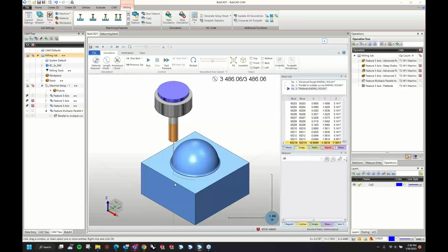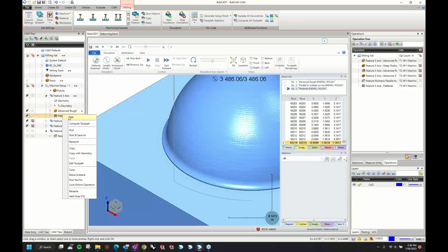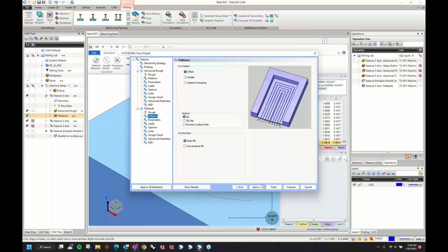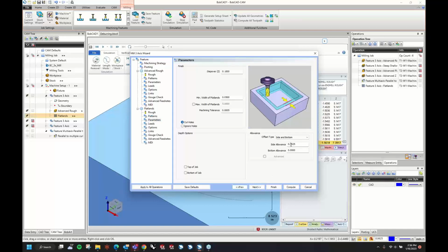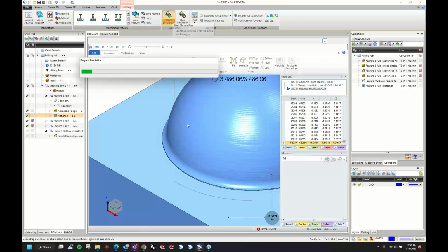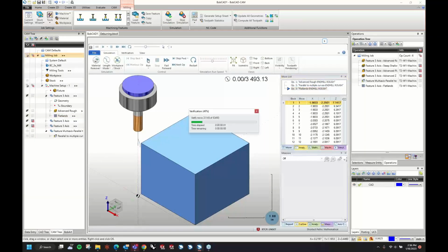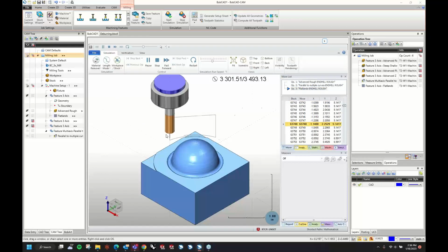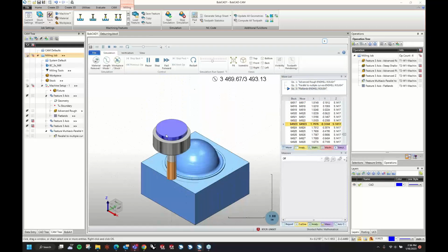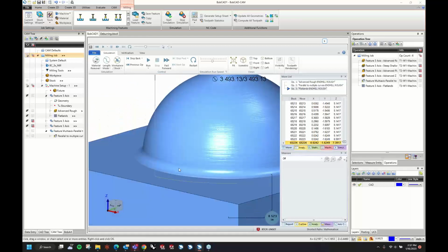Yeah, I know what it is. I need to have the tool a little further away on the flatlands. That side allowance probably needs to be about an 1/8 inch to get that full radius on there. Just had to go in a little too far.